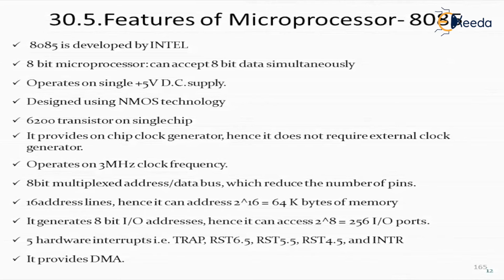It has 6200 transistors on a single chip. It provides an on-chip clock generator, hence it does not require an external clock generator. So the clock is itself present on the 8085 processor. It operates on a 3 megahertz clock frequency.